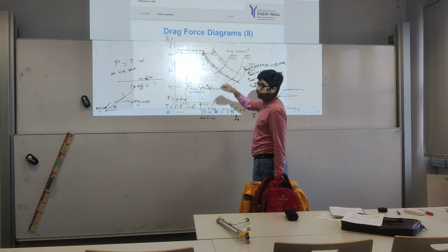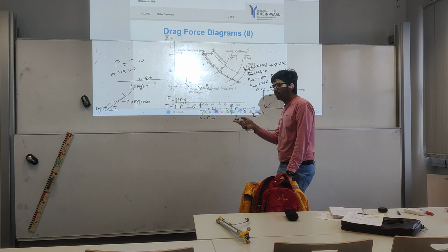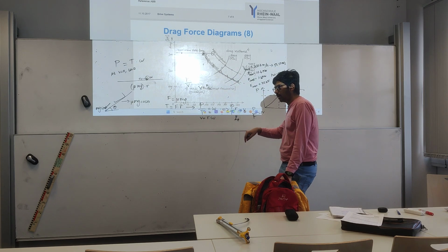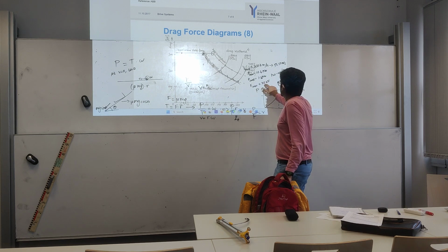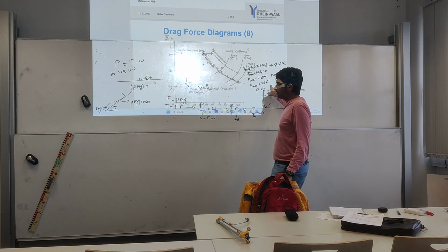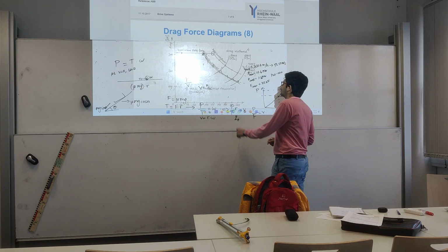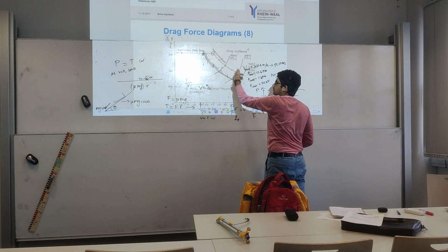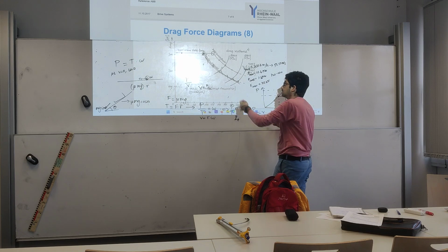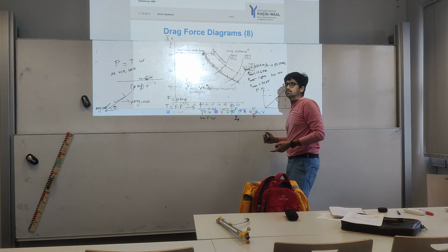If not, to get these two points, we just have to divide the different powers by the tractive force, the maximum drag force. In this case it was given, but if not, it's just mu mg. That's all. Then you get those points. Then you take constant power, take higher and higher velocities, then you get more data points on this curve. That's all.